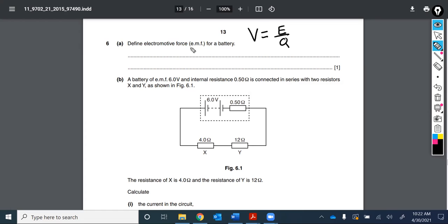But you really do need to distinguish between this type of voltage and potential difference. The terminal PD at the battery, the e.m.f here, the potential difference across the resistors, all of those are voltages, right? So we need to distinguish that. One energy consideration with e.m.f is that here is where we're converting other forms of energy. In this case, a battery converts chemical energy into electrical energy, and again, per unit charge. So that's the energy consideration.